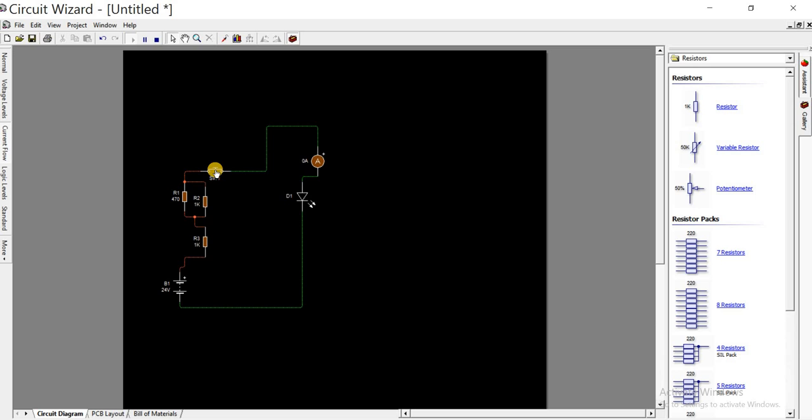The reason why we use series and parallel connection is that at times you will need a certain value of resistor, maybe to get a certain value of current, since you already have your voltage fixed. In that case, we need to manipulate, and that resistor is not available in markets or in your workshop. So you need to manipulate the value of the resistor by using series and parallel connection to get the total value of resistance that you need.